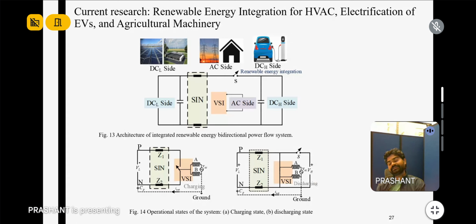To drive that, to store the energy in the battery or to take the power from the battery, we should have some DC-DC converter there. So for an AC motor, we need a DC to AC converter, that is an inverter. For the battery, we need a DC-DC converter, buck boost. For different applications, sometimes we need an AC to DC converter.